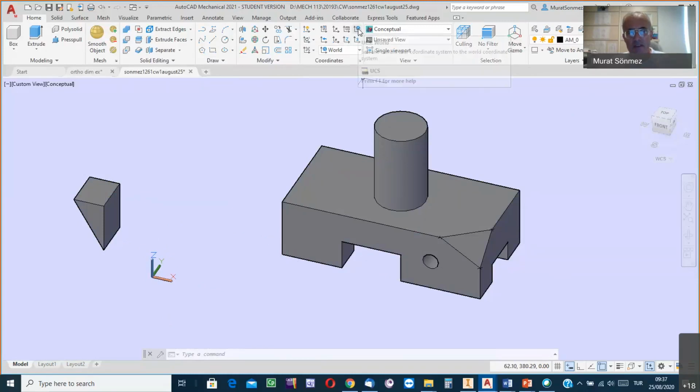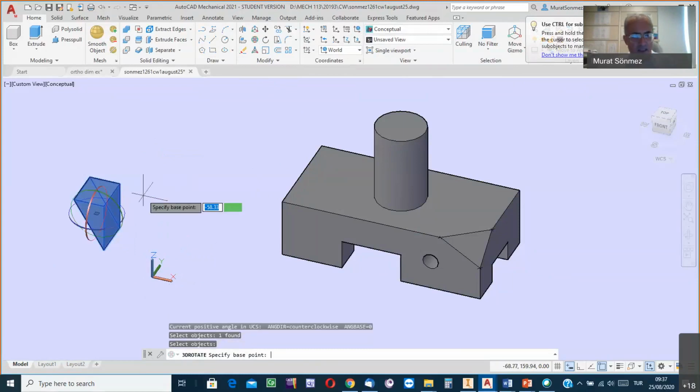I said to click on this button to have the coordinate axis symbol at the world place, at its absolute location. Then, after having the coordinate frame at the absolute location, when you start the rotation process and indicate the green ring, you see the simulated line, the axis for the ring, is parallel to the y-axis.